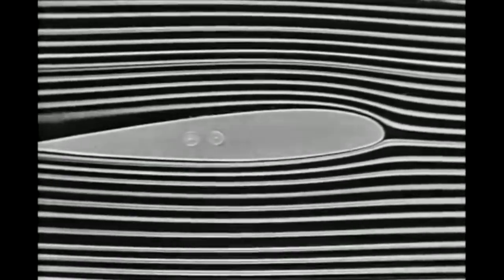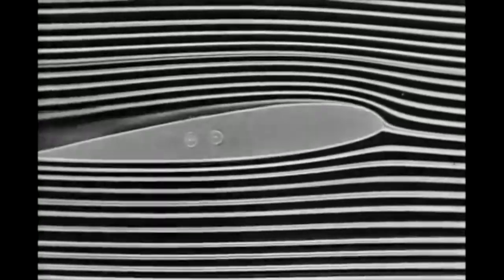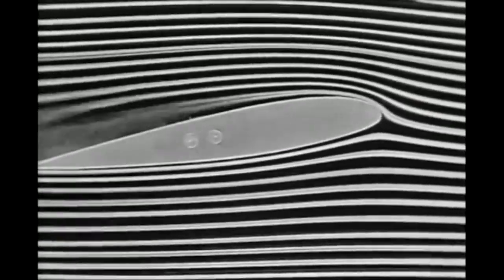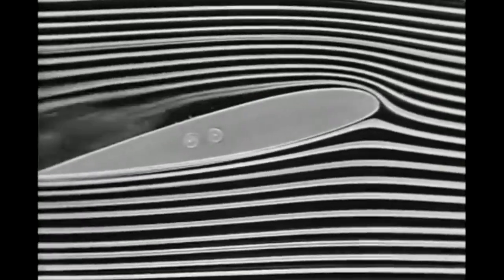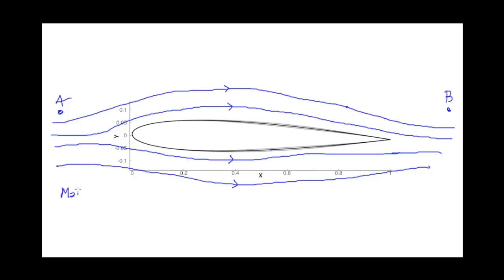So when air flows from A to B, its field is disturbed by the presence of the airfoil. It generates a separation of the flow due to its presence. So when the air encounters the airfoil, it generates a pressure field along the airfoil. Okay, remember that when there is fluid flow, we have two main forces that the fluid exerts on a certain body.